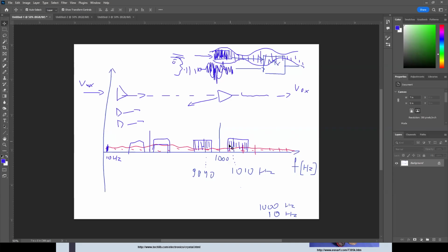Okay, so here is a sideband, because we have many frequencies when it comes to voice. So it's not just a single spike, it's a band, a sideband, or a certain area that requires a certain bandwidth. The sums of all the frequencies present are going to create the upper sideband on this side, and all the differences are going to create the lower sideband. So here's the upper sideband, and here's the lower sideband.